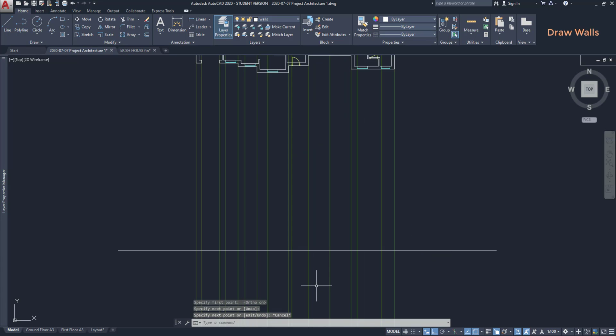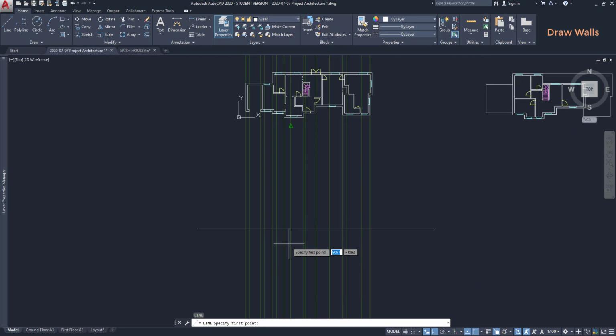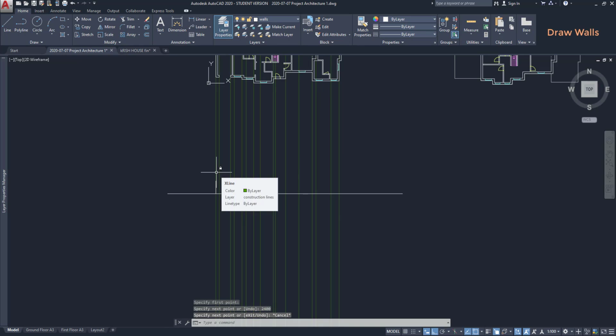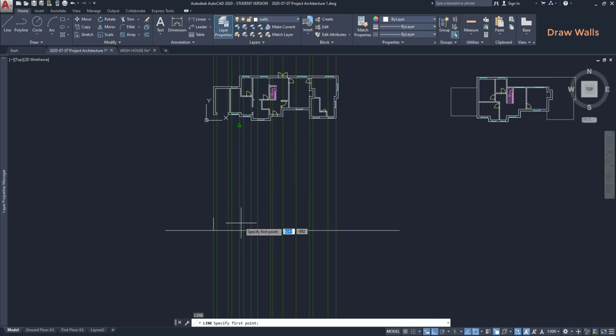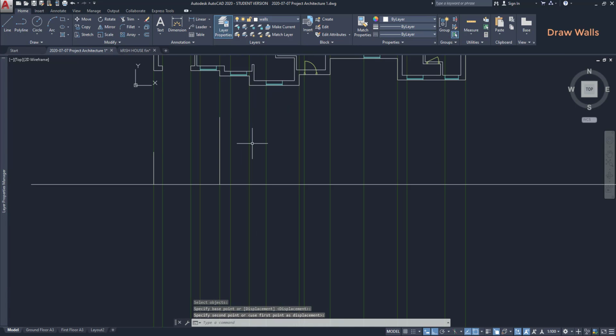Now I'm going to draw the walls on the elevation plan. The first and the last ones have lengths of 2400 because those parts have just one floor. All the other lines will have a length of 5000, like the second one that I'm going to draw. I move that endpoint. Then I start from here and type the value 5000. Now let's move the elevation a bit closer to the floor plans to be easier to work.